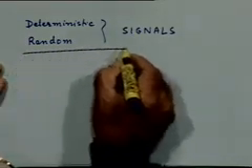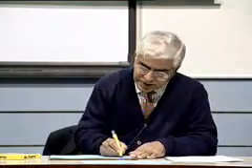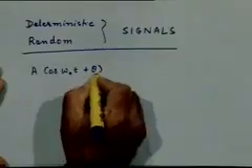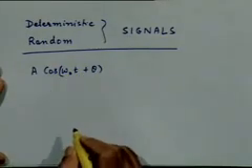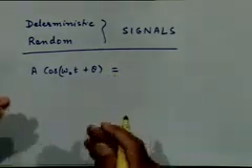The most basic kind of deterministic signals which you come across are complex exponentials and sinusoidal signals, real sinusoidal signals, right? So if you take a real sinusoid, like a very simple signal like this, right? We know some of its features, but as you must have already learnt, you can express a real sinusoid or cosinusoid in terms of complex exponentials, and it's much easier to work with complex exponentials in many instances than with the corresponding trigonometric function. Right?